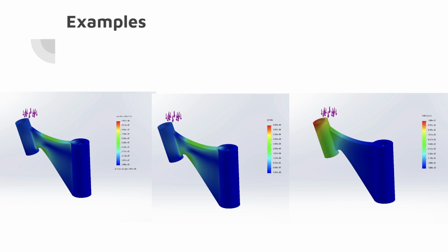Maximum deviation, right? Once again, strain: you can see where the strain is. You can see how my design is bad, because it's a really weak point right here where the stress is max. So you just right click and click show to display it, and that's brilliant.